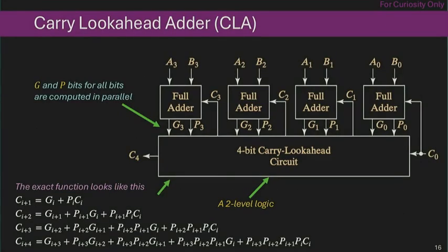And that is the idea of a carry look-ahead adder. A carry look-ahead adder computes the generate and propagate condition for each individual bit, and then sends it to a master look-ahead circuitry. And this circuit will compute each carry in a 2-level form. This is a very complicated expression, so don't worry about this.